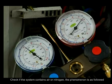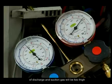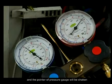Check if the system contains air or nitrogen. The phenomenon is as follows. When it is running, the pressure and temperature of discharge and suction gas will be too high. Current will be too large. The compressor has abnormal noise, and the pointer of the pressure gauge will shake.